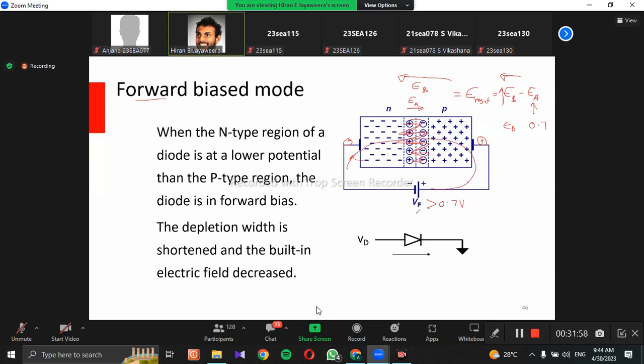But if the battery is the other way around, you can't let the current flow. So basically the PN junction works as some sort of non-return valve. And this is a model for the diode. The diode is the kind of concept that people wanted to have: in one direction, it allows current to flow, and in the other direction, it blocks the current flow.